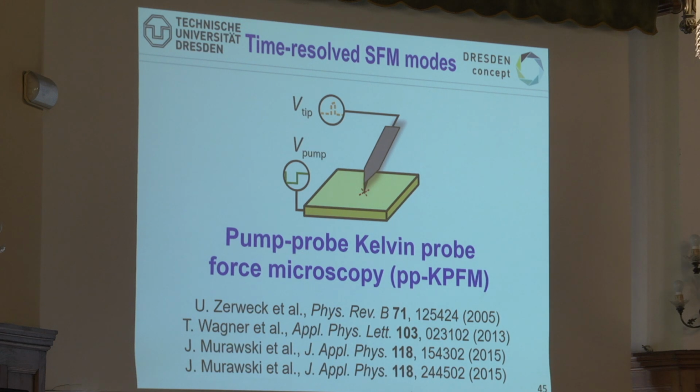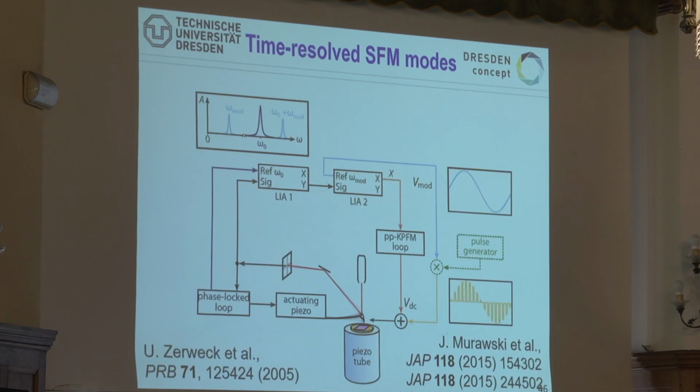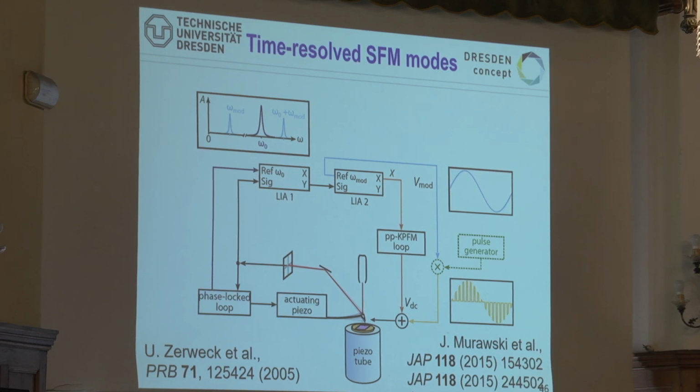And exactly we have been setting up such a possibility to say, well, my tip and my sample can do much better things rather than actually only applying DC or AC voltages. And the idea was actually born to say, okay, instead of using this sine wave only for demodulating, remember we apply an F0 voltage to my cantilever in Kelvin in order to make this sideband. Now let's make this a little bit more complex.